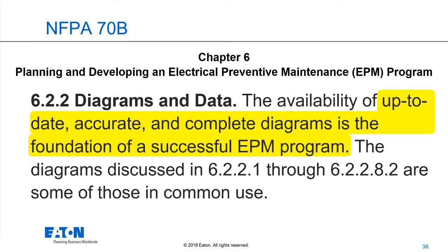And every time you get into doing maintenance, a lot of people say, well, I never had time to keep my one line diagram updated. I think that's a cop out, in my opinion, because if you didn't have time to do that, it means you probably didn't have time to do your maintenance on your power distribution system, because while you're doing maintenance is a great time to keep those documents up to date.